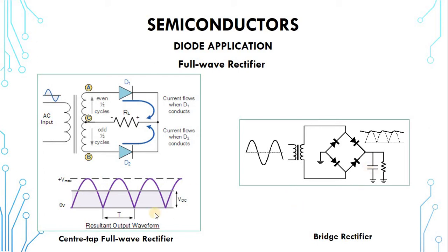capacitor. So at the end of the day, though the current rose to maximum and is beginning to drop now, though that one is dropping to zero, the load is not going to see the one that is dropping to zero, because it is now taken from the capacitor that is fully charged. So as current rises, the capacitor gets fully charged. As current is dropping, the capacitor will now serve as a source of supply to the load.